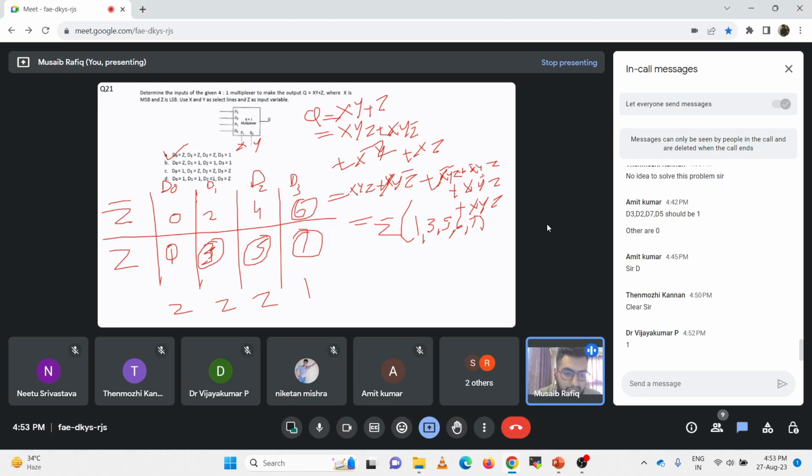Z was your LSB, and your LSB is connected to your input. When we did that implementation earlier, the MSB was connected to the inputs, not the LSB. So that's the difference. In the implementation table, you need to change the format, because if you look at the truth table of ABC for a three variable system, A remains 0 0 0 for the first four cases, then it is 1 1 1 1 for the next four cases. That's why 0 1 2 3 comes in the A bar line, and 4 5 6 7 comes in the second line. Here you have an LSB, which changes from 0 to 1, 0 to 1, 0 to 1, 0 to 1. That is 0, then 1, then 2, then 3. So that's why it is 0 1 2 3 4 5 6 7 in one case, and when it's the MSB, you write it the other way. I hope you got my point.